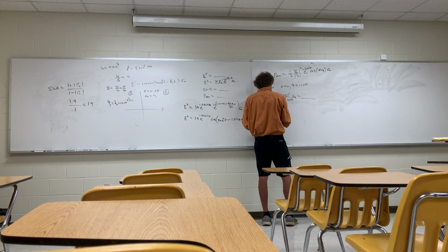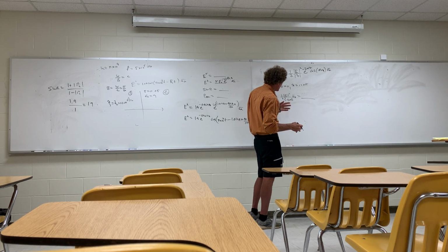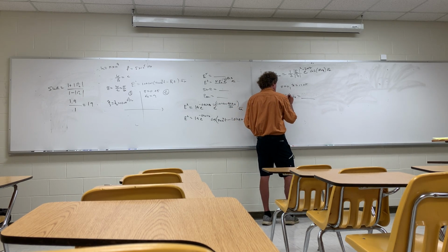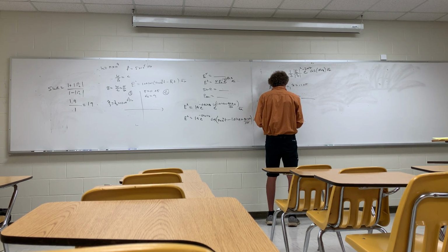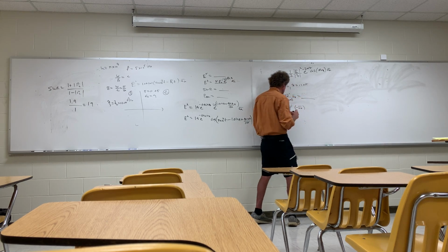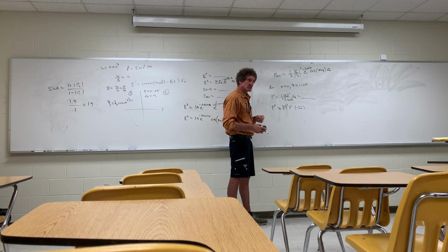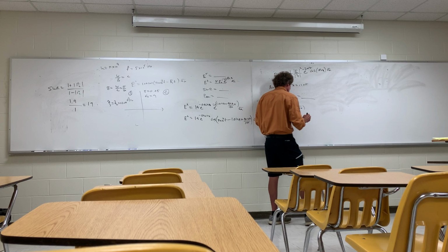For the reflected wave, everything's the same except power's going the opposite direction. Instead of the incident E field value here, E naught incident, now we're gonna have E naught incident times the reflection coefficient. But what this really will be is the reflection coefficient squared times the incident power density. It would be in the minus AZ direction. I'm simplifying the math. I could go ahead and put down, it's actually 1/2 E naught reflected squared over 120 pi in the minus AZ direction, but really the only difference between this and what would be written here is the gamma squared term. Y'all follow me, class? So for this one, we'll get it in a second.